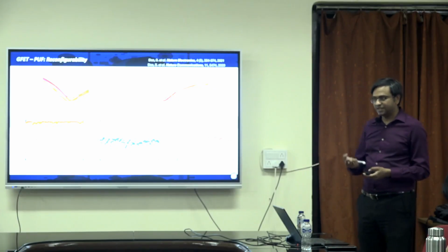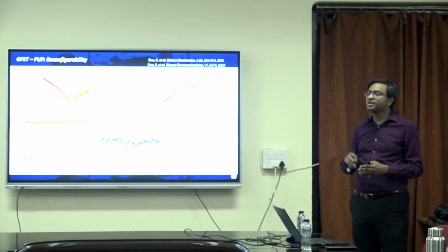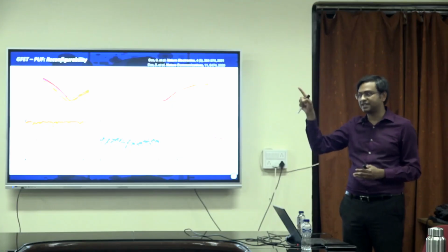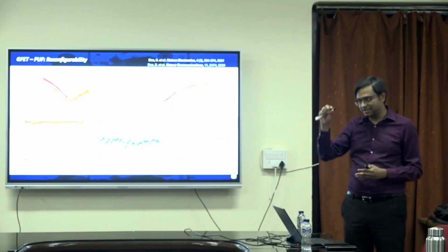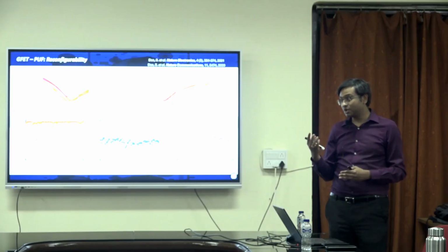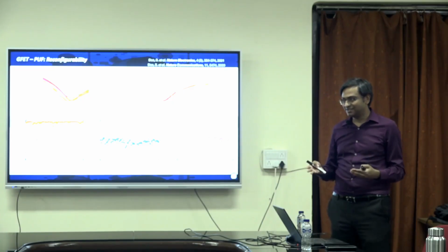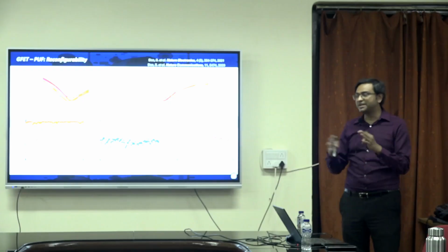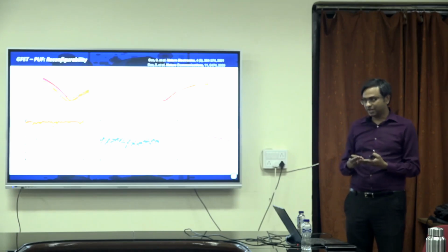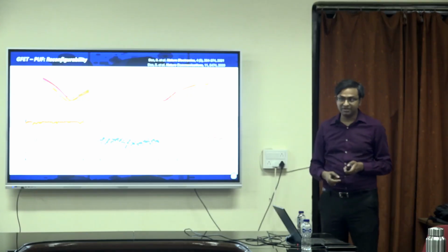Just by applying bias. Like in a memristor device, you apply this forming process and different cycling processes. I do not know how much you have seen memristor devices, but even if you measure the memristor devices for multiple cycles, there will be a band. After every cycle, the conductance is a little bit different. It's not exactly the same, and we are using that variation. So if you do not make a good memristor, then you are even better, because every time it will give you a different result. But once it is formed, and if you do not form it every time, it will keep giving you the same result. It's almost like a non-volatile memory, which is programmable. The number of states it can go through, you can have that many number of reconfigurations.